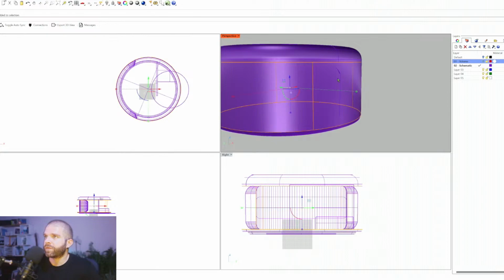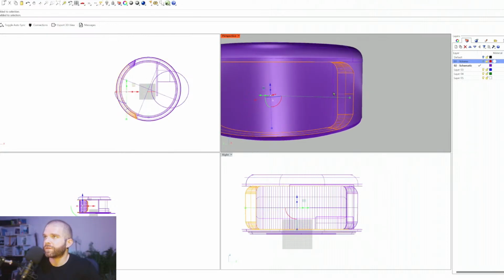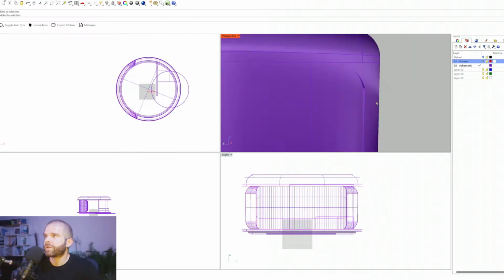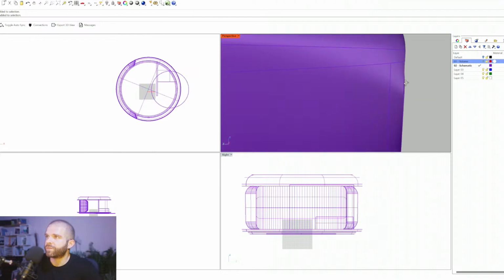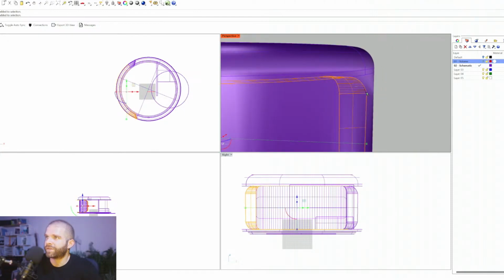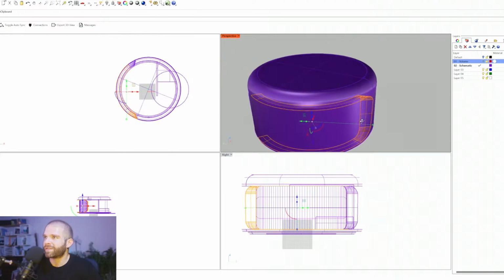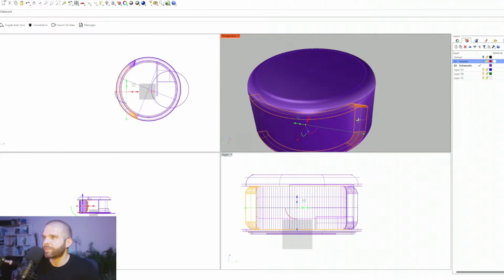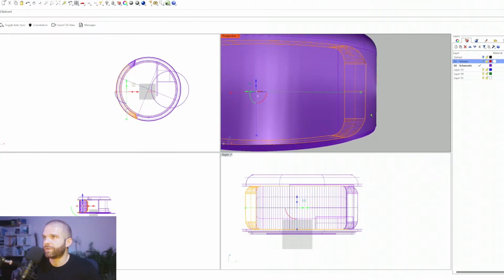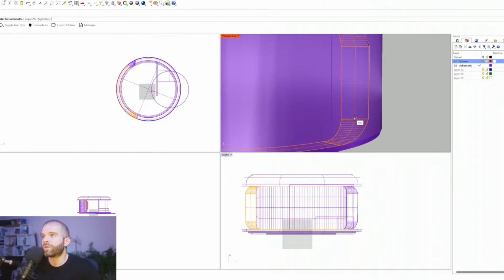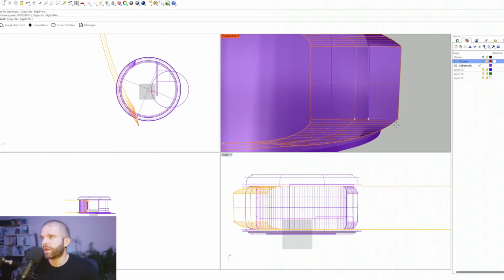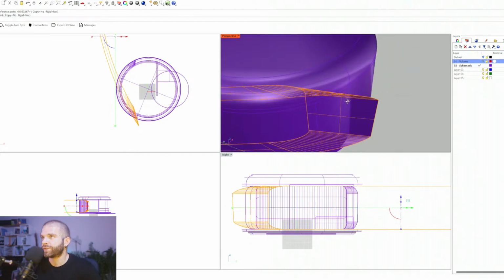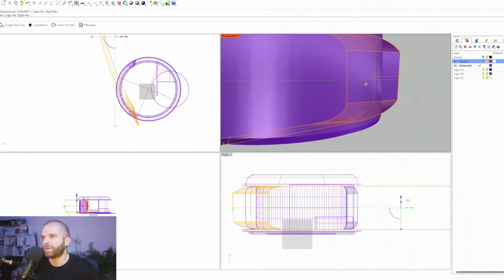We'll try this trim thing again, since now we see that it's peaking a little bit, but not as much as I'd like out of that other surface. So let's copy paste it again. And you know what I'll do is scale 1D from its center to its edge outward. So it should just be extruding in a straight line.